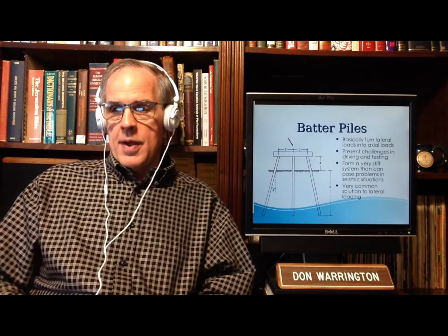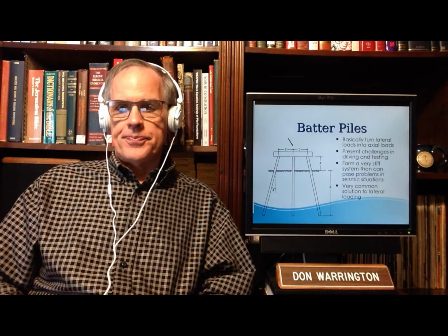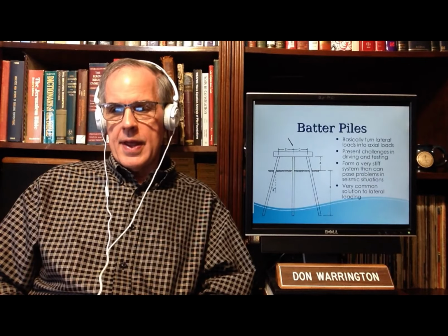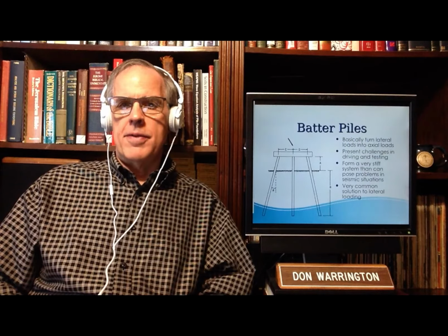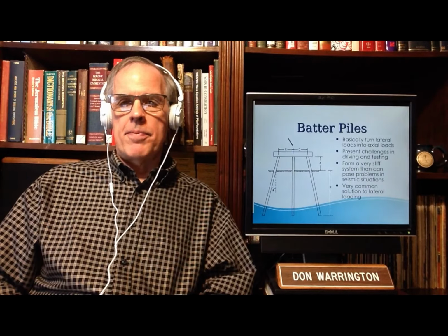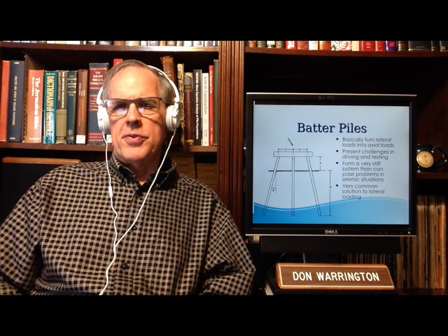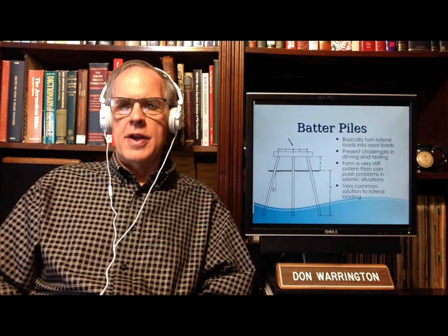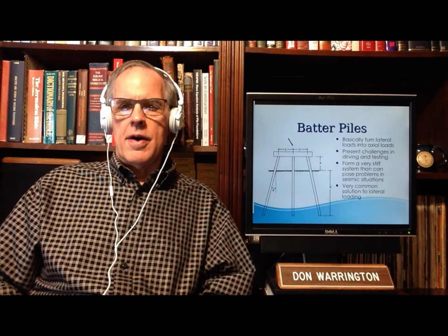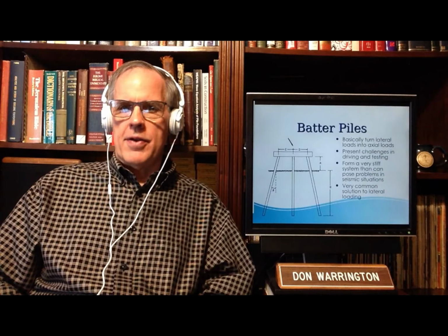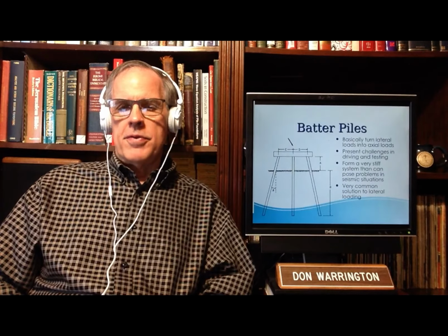Battered piles, I've talked about them before, are basically an angled pile. This is mostly with driven piles; you don't see many drilled piles driven at an angle.